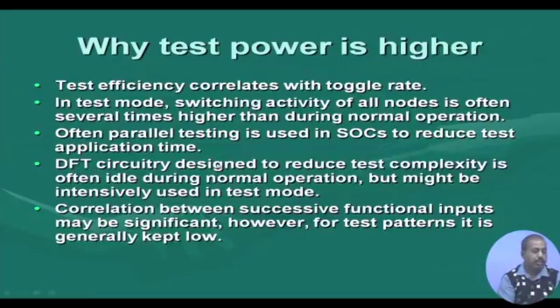Then, DFT circuitry designed to reduce test complexity is often idle during normal operation, but might be intensively used in test mode. We have already seen the scan chain and all that. They are not active when the circuit is operating in the normal mode, when only the normal operations are taking place. There may be some error detection circuitry, and then the BIST that requires the test pattern generator and response analyzer to work.